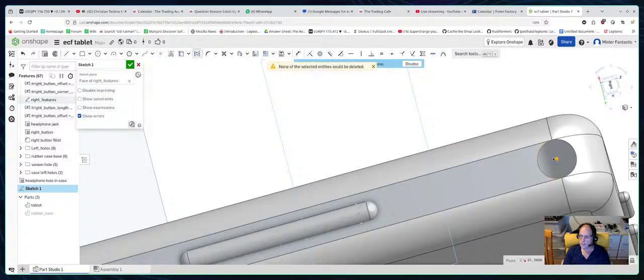Okay. Let's make a new circle. Use the same center point and just make it 5 mil. That's a little bit extra. Great, done. Probably we should be using some variables, which is like headphone jack width. We don't want it to be a guideline. We want it to be a real line. Okay, not a guideline.